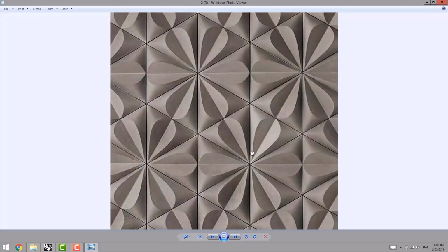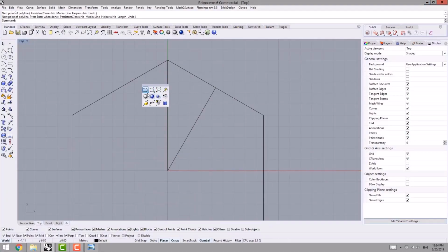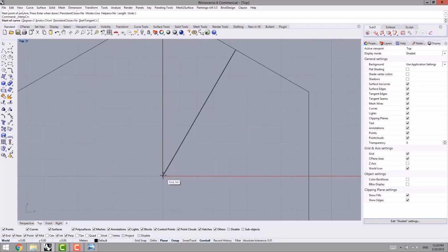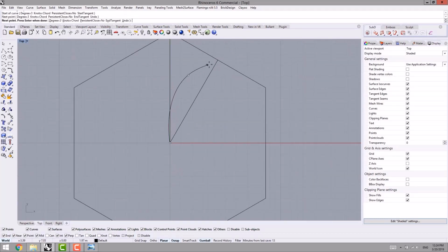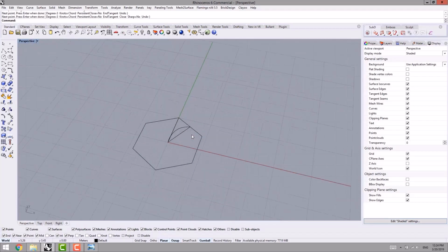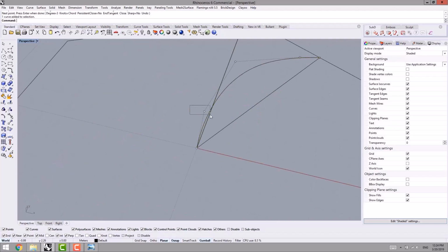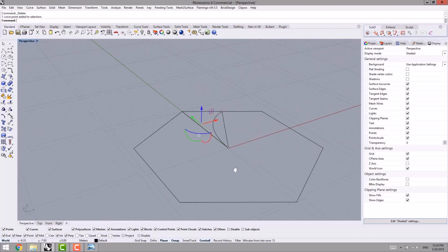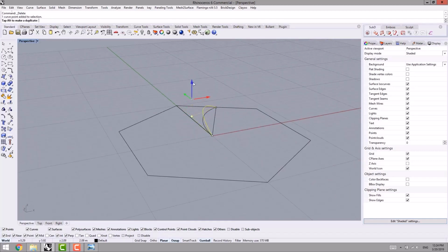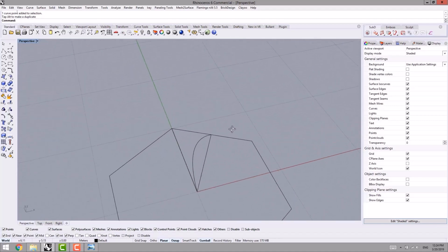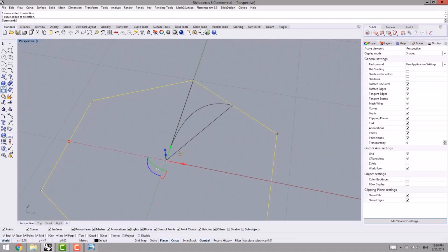Then I need to sketch a curved line as you can see on the scene, and then to create one of these parts then we can array it. I pick curve interpolate points. I start the command and then this way, by specifying 3 points, I sketch the curve like this. Then in the perspective view, I select the line or the curve actually. Then I remove these 2 control points. I select the mid control point. Then I move it upward, as you can see on the screen.